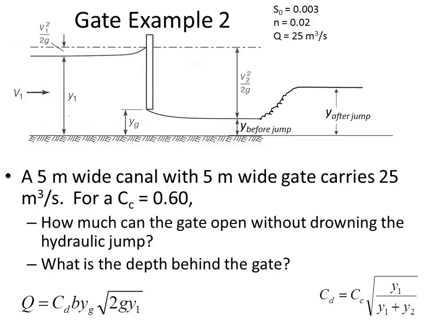The procedure is fine, but I'm afraid I've selected some illustration values that don't illustrate very well what's going on, because I think we've got two mutually exclusive things in the values I've selected for the example. We've got a critical depth of approximately 1.4 meters, and we should only see a jump if the depth is less than that. I guess now it's starting to make sense to me.